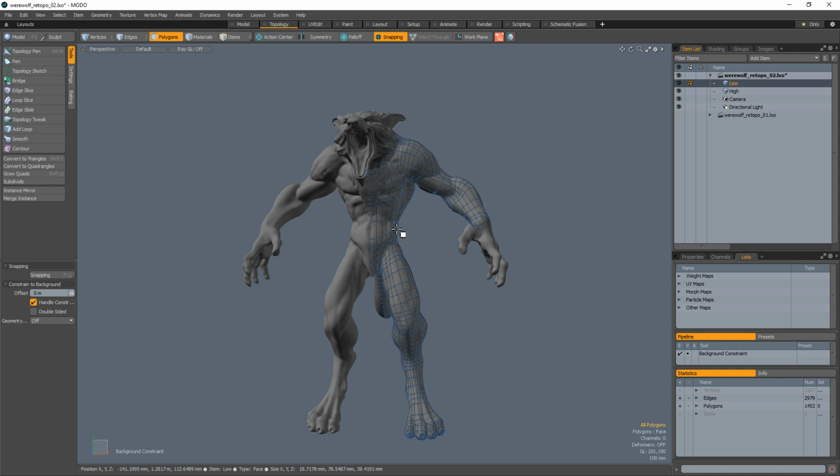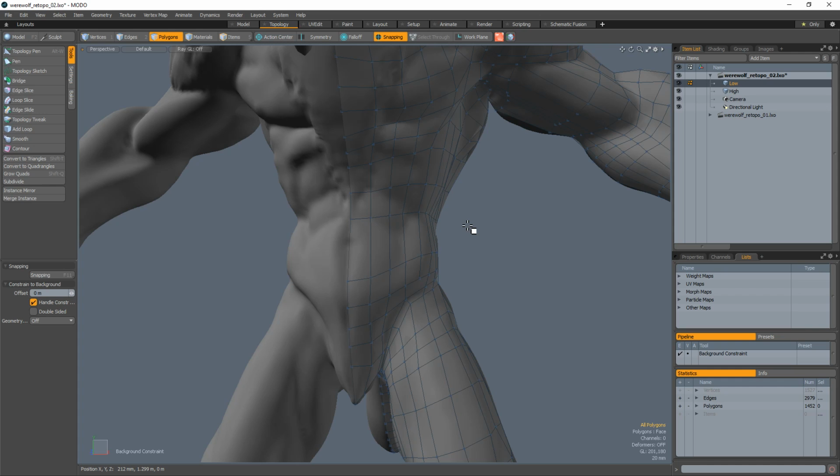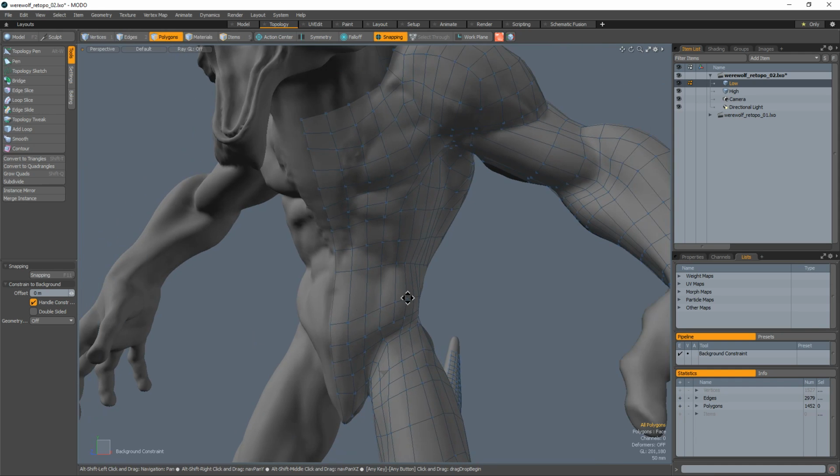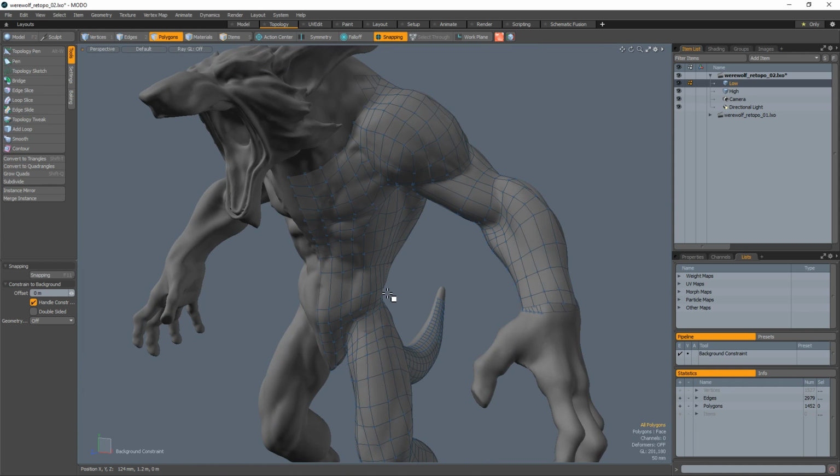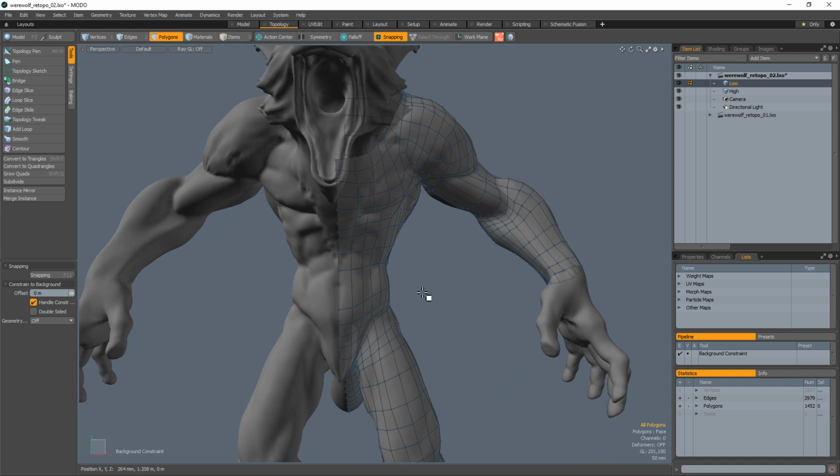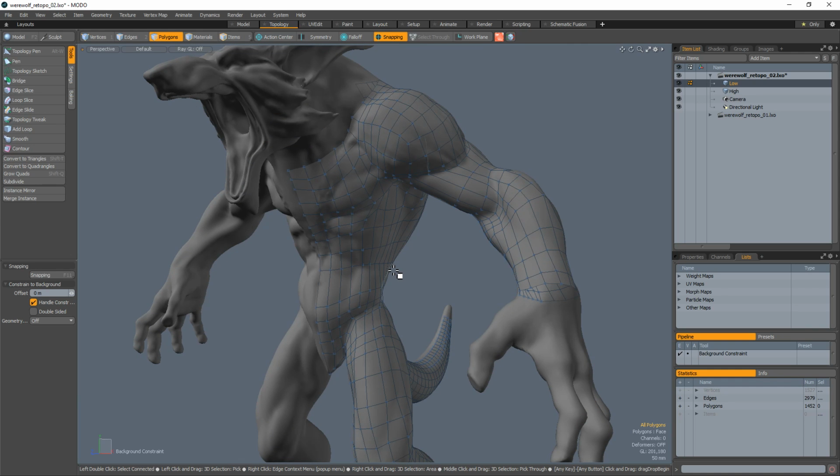So, polygons subdivide. We subdivide polygons all the time for things like subdivision modeling, for making stuff in ZBrush, for baking things out from a high poly source to a low poly. And there are lots of ways to lay out polygons. Obviously, there's an infinite number of ways. However, there are some best practices you want to keep in mind when you are modeling characters, especially characters like this guy right here, who have very organic shapes and who you'll probably want to sculpt on a little bit.